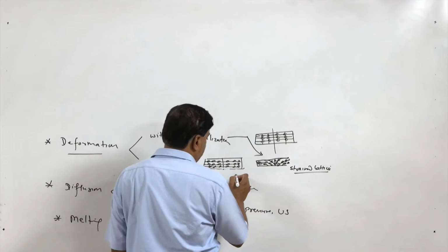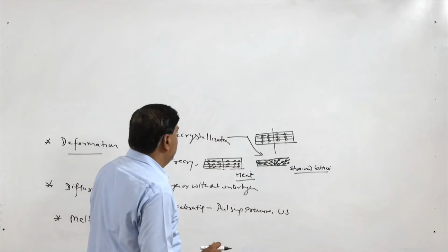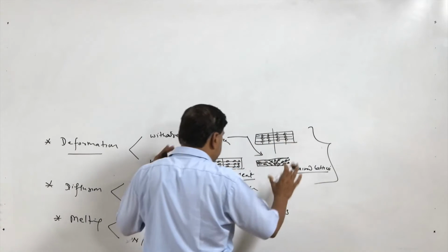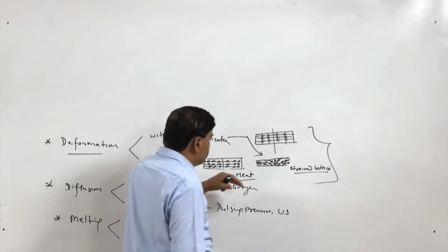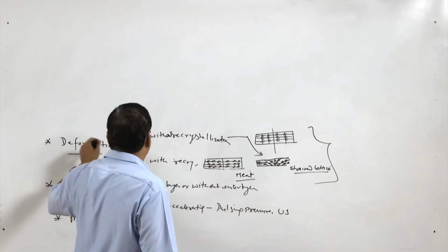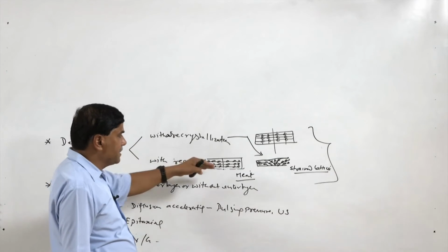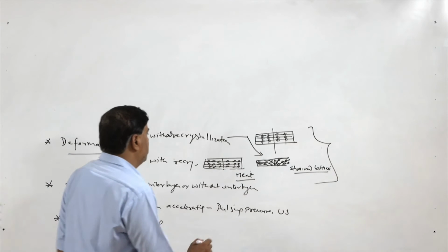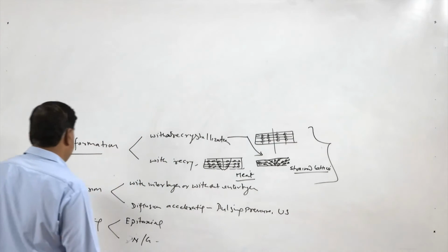So, this happens when a lot of heat is generated in the course of the welding. Here the heat generated is limited. So, these are the deformation based joining processes where heat generation is limited. You will see strained lattices and disturbed arrangement of the atoms, and otherwise when the recrystallization takes place, with deformation and recrystallization, when sufficient heat is generated, the normal arrangement of the atoms is achieved. So, you will see that there is a joint, but the arrangement of the atoms has not been disturbed much.